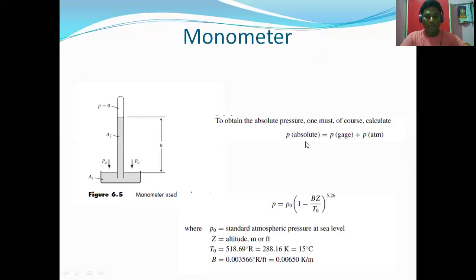Such a measurement might be performed with a mercury barometer. Therefore, local atmospheric pressure can vary between the inside and outside of a building because of ventilation systems. Okay, and the common mistake made by novice experimenters is to take the local atmospheric pressure as the value given by the local weather station.